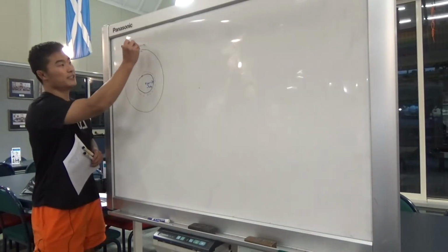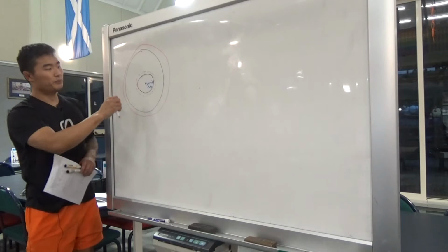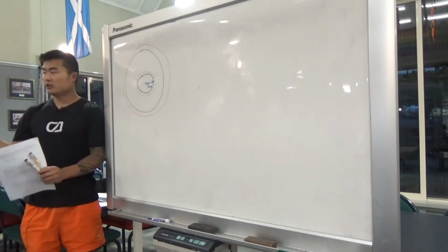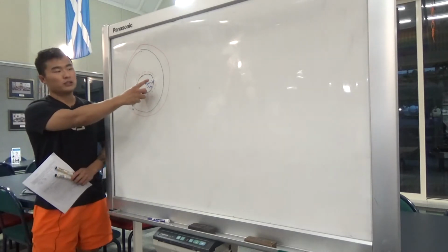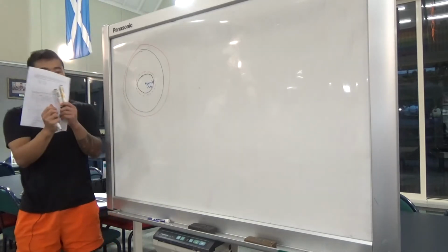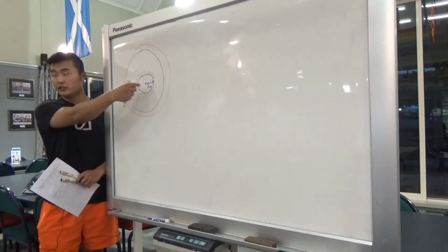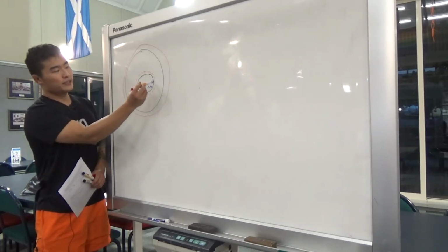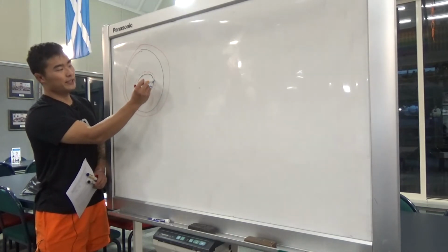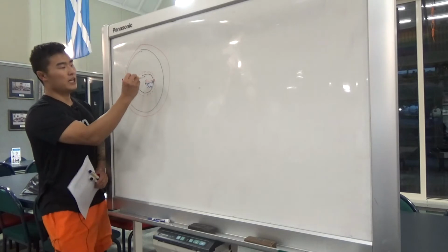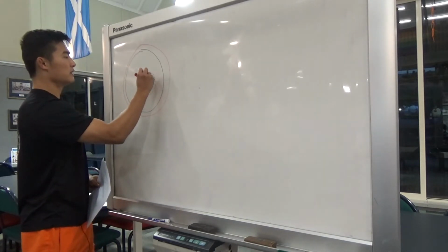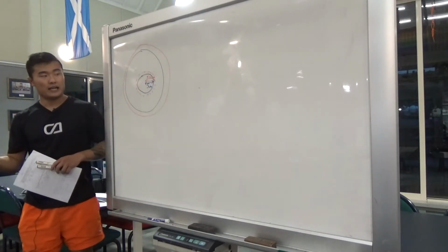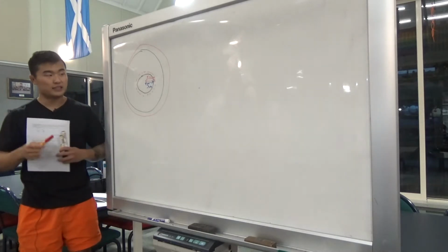So this whole plate is going to expand, and because there's a hole in the middle of the plate, when the plate expands, you might think that the hole might get smaller, but what happens is that everything moves outwards, okay? So the hole is also going to get bigger, right? So the radius of this hole is going to increase. The radius of the hole is now going to become 5.01 centimeters. That's a bit of an exaggeration regarding the increase of the size, but just so you can see.